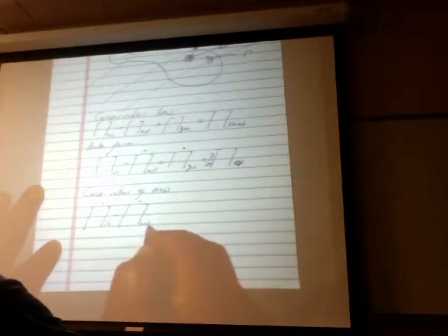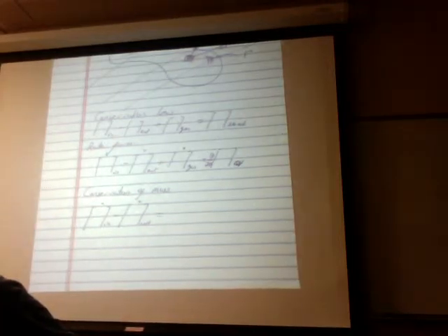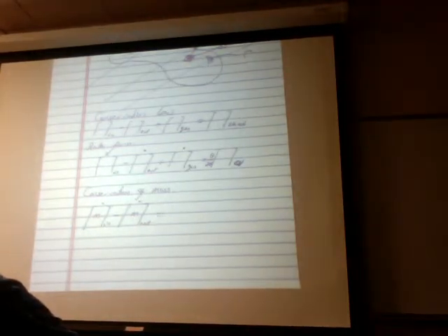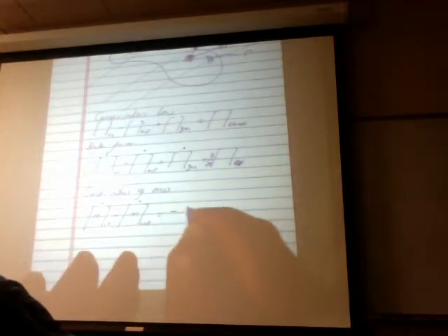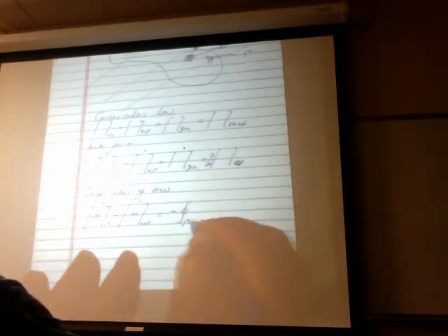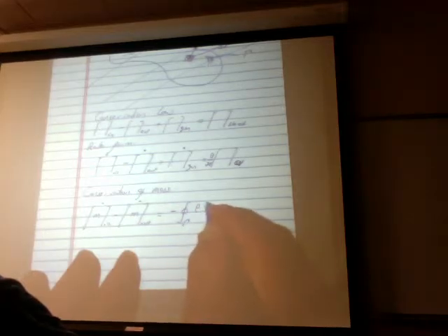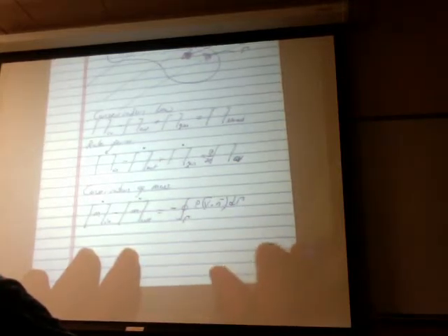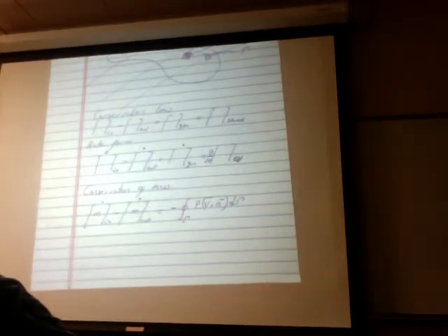So this is the net rate of mass coming in. I'm going to call this M. The net rate of mass coming in and out of the control volume is minus the integral over the surface of rho v dot n d gamma. Okay, and let's try to dissect that particular term and see why that is the amount of mass leaving and entering. It's actually the net amount, in minus out.